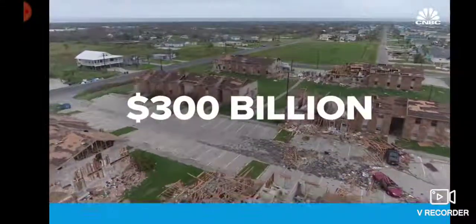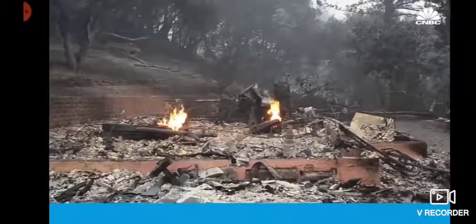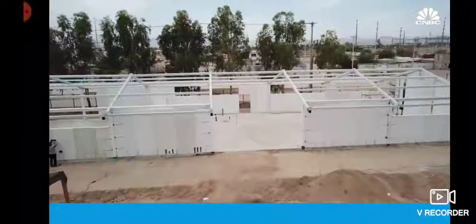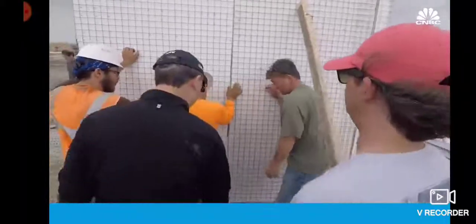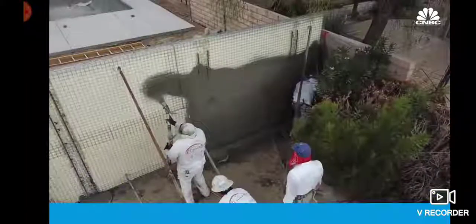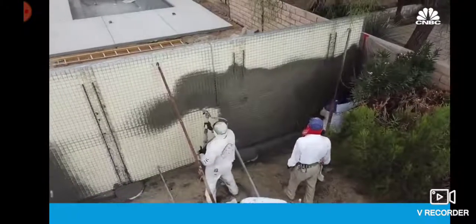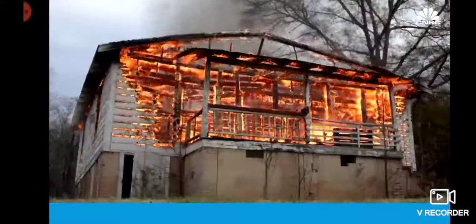There was a record $300 billion in disaster damages in the US in 2017, with devastating fires in the West and hurricanes in the East. Ken Gallagher is the CEO of RSG 3D, one company that wants to help. It's bringing a building material known as a 3D cementitious sandwich panel to the masses in the US. Each panel consists of fire-retardant foam sandwiched between two wire mesh faces. The two faces are connected with reinforcement wires that run through the foam, and the whole thing is enveloped in concrete. It's very strong if built properly and can withstand high winds, earthquakes, and even fires.